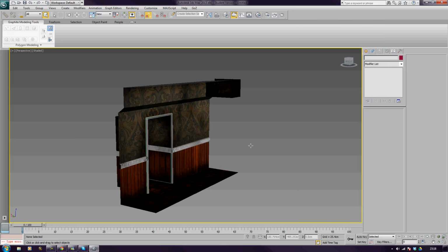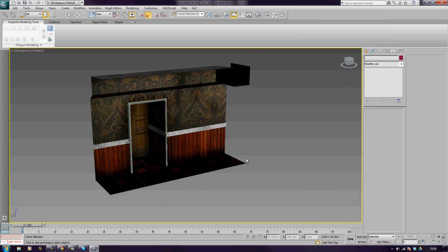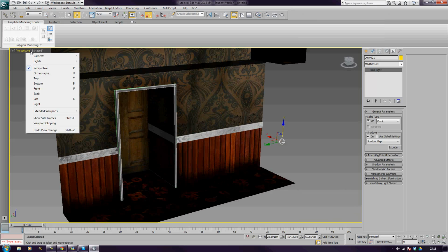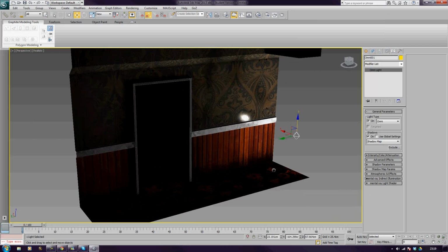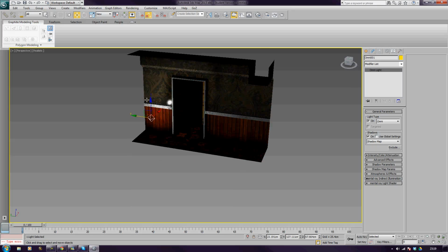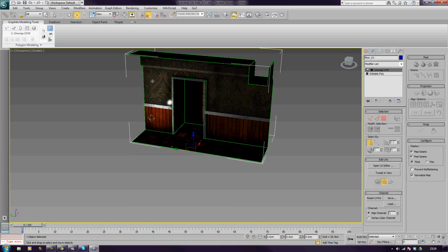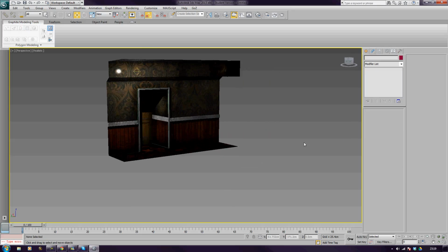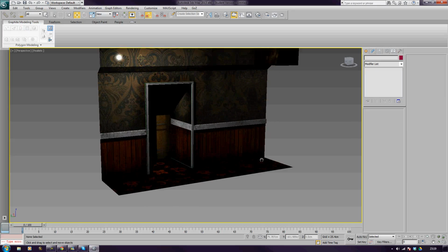And now, with all these textures applied to this, what I can do is just stick a simple light. Nothing exciting, just stick that there. Make sure shadows are on. And change shaded to realistic. There we go, so we can see the actual lighting effect it's going to have here. Maybe bring that up to about there. Whoops, wrong one. Okay, because we haven't actually built a light into the scene yet. And I'm just going to hit render.